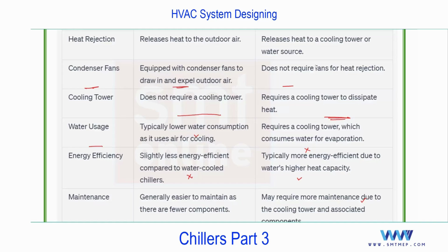But that is not the only point, because in some cases the outside temperature is above, suppose it's 40, 45 or more, but there is scarcity of water. In that case there is no choice for the water cooled chiller. You need to compromise with the air cooled chiller. But if you have both, in that case, you can take the decision accordingly as per the condition.